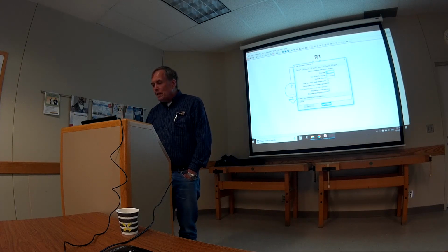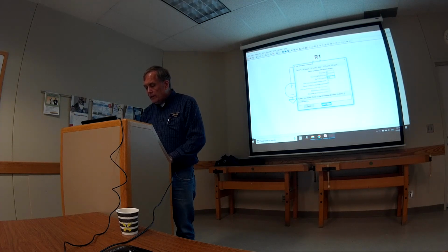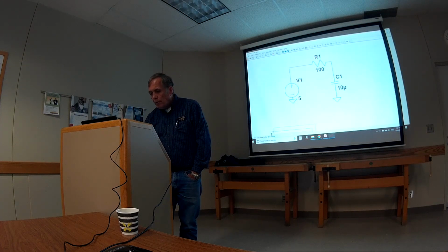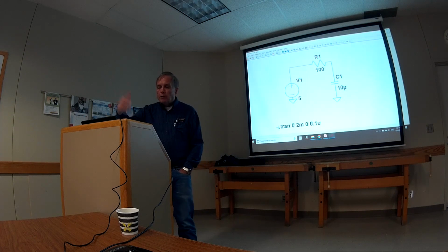So 2M is 2 milliseconds. I want to start right at 0, and I want to say a maximum time step of 0.1 microsecond. You can vary that, but that's just a good starting spot. I'll put this down at the bottom. You just paste that on the bottom, and Spice will pick it up.